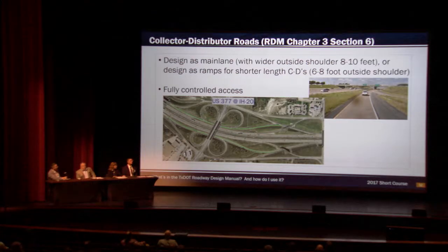So really for high speed, it's only good for about 15 miles an hour. So it really wouldn't meet today's principles. So it is a lot more challenging in some of the compact urban areas to meet those principles. You're going to have flatter curves, and you're probably going to have a super elevation on those. And really, it's more for safety and trying to get your wider shoulders out there.